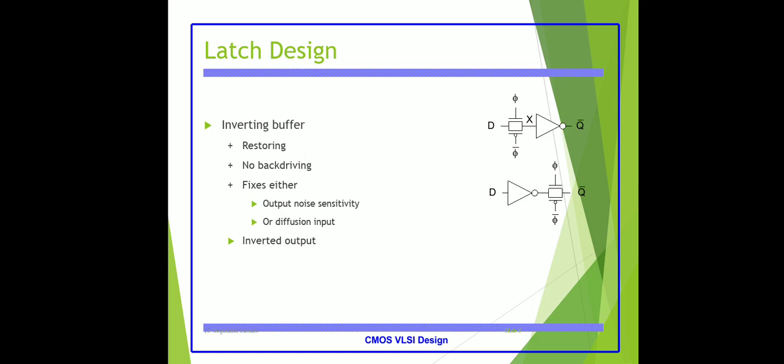So these latches are the basic storage elements that can operate with signal levels. Also it can be controlled by the clock transition or flip flops. So these latches are level sensitive devices which are useful for the design of synchronous sequential circuits, and also these latches are sequential circuits with two stable states that are sensitive to the input voltage applied, and it does not depend on the clock pulse.